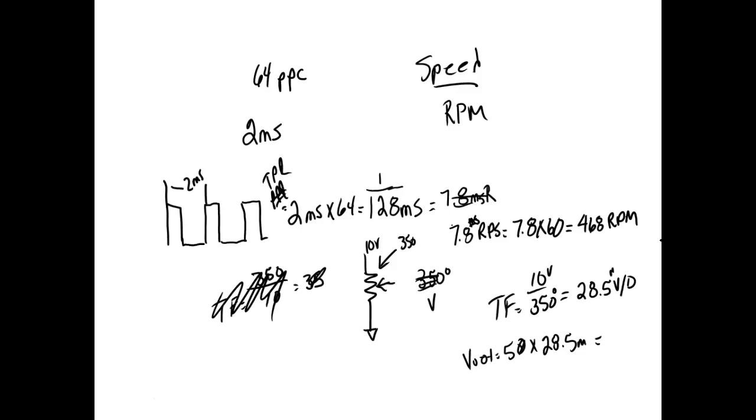Right? You understand? So in your house, if you've got a thermostat, what does the thermistor on your thermostat do? It gives a voltage that represents a what? A temperature. But when you go over to your control, you don't set a voltage, you set a what? You set a temperature. Well, if it didn't know what 4 volts was, then it would mean nothing to the control circuit.